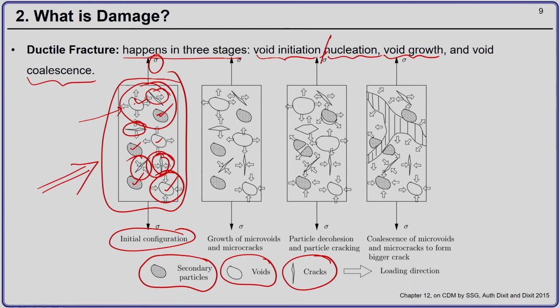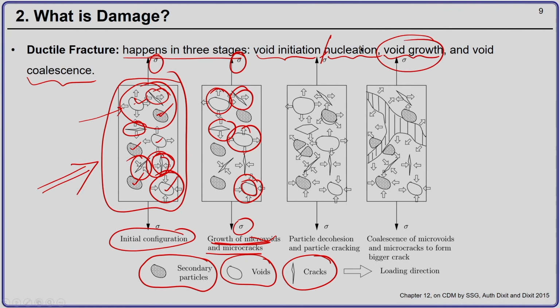Now, once you apply the load and increase it, these voids or cracks which are there will grow. Although the ends will not grow, the size of the crack or the voids will grow. This is called the void growth phase. Also, at this point you will not have any new voids coming into the picture.